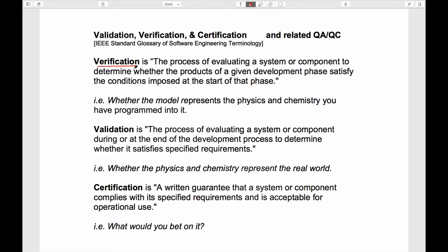Maybe you're using a linear thermal coefficient of expansion instead of the volumetric coefficient of thermal expansion, which would be a factor of 3 off. If you don't know that, you will end up with numbers which are not true to the system you're dealing with. So verification is one important thing in making sure that you are getting the results that you want.